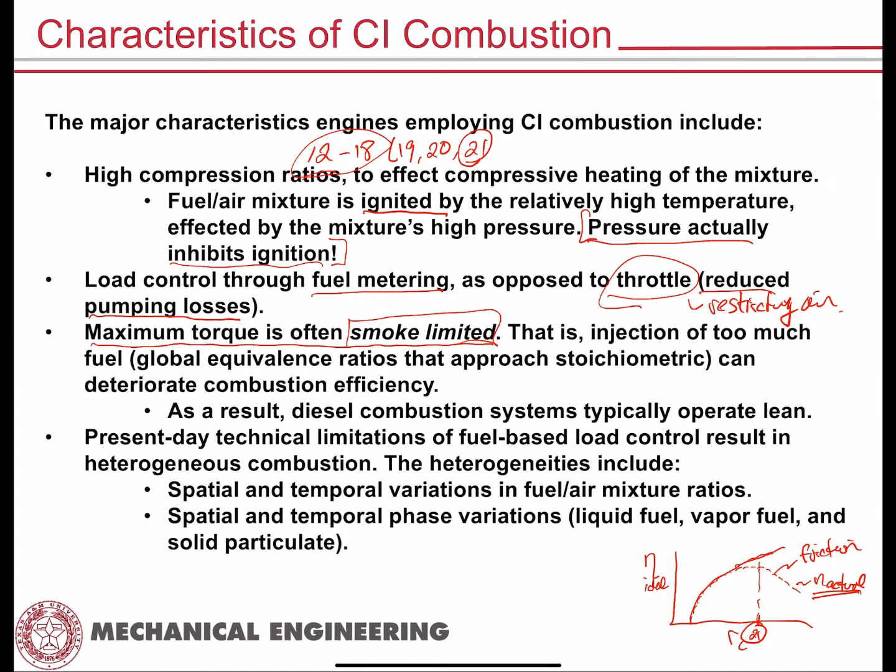And you create what are called locally rich regions, which basically occur when certain parts of that injected fuel, say the first droplets of fuel that are injected, undergo those physical and chemical processes rather quickly, and so they ignite soon as you're injecting more and more fuel into the cylinder.